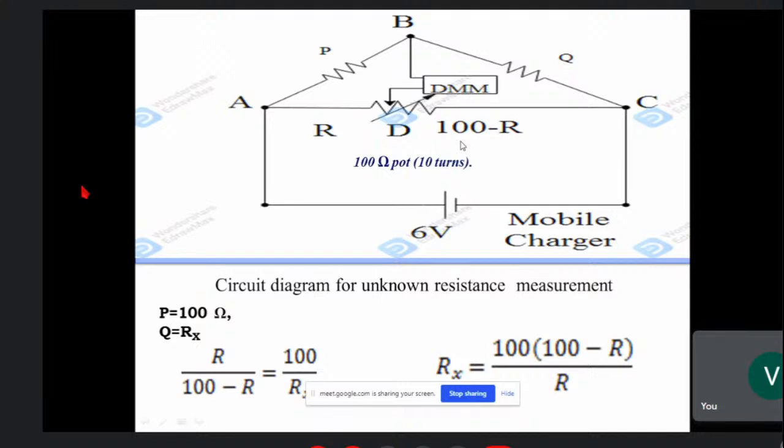these parts. Your central part, when you rotate the spindle, it moves along this direction. So when you put it at one end, it will show you 0 in principle. And as he is saying, about 5% tolerance is there, so it may be within 2-3 ohms difference. When you put the spindle on the leftmost part and rotate it to the minimum point, it is in principle coincident with this point, so it will give 0.